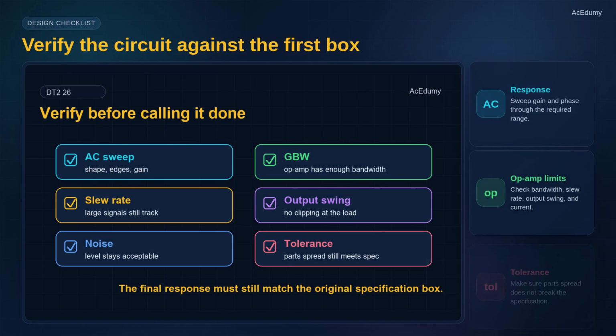Before calling the design finished, run a verification checklist. Check the AC sweep, the gain bandwidth product, slew rate, output swing, noise, and component tolerance. Then inspect whether the response still meets the original specification box.